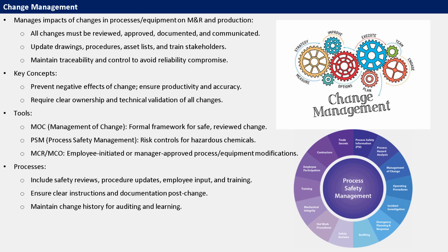Ownership of changes must be clearly defined. Someone must be accountable. Every change should be technically validated. Engineering check, impact assessment before execution. Changes must support productivity, safety, and accuracy in operations and maintenance. MOC, management of change, a formal, documented process used especially in industries like oil and gas or chemicals to manage change safely. It includes hazard assessments, approvals, and procedural control.